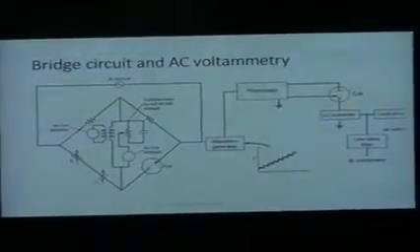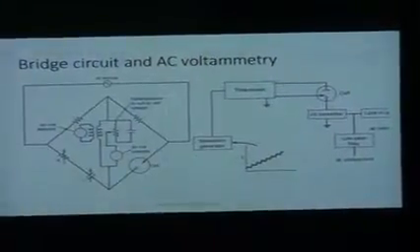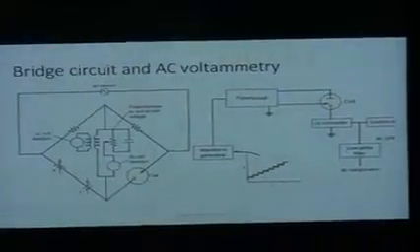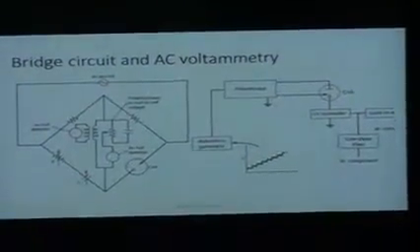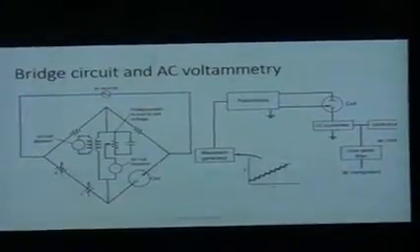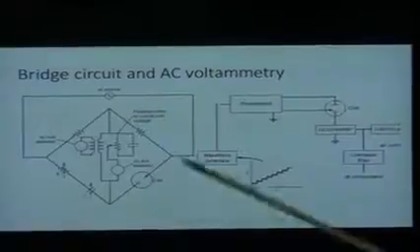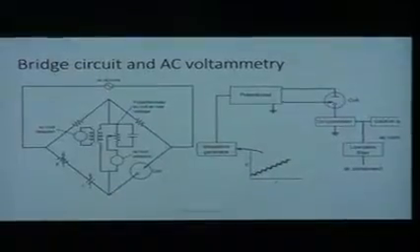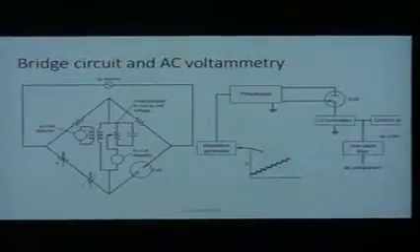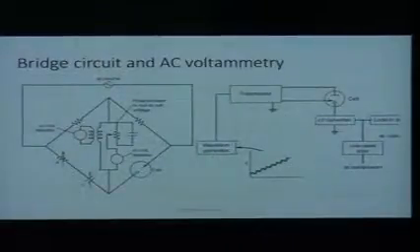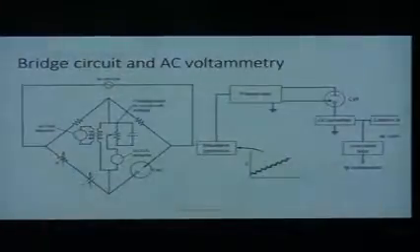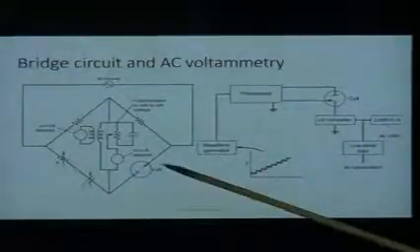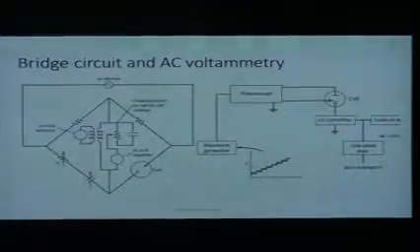So the way to measure this, there's a couple of different techniques or circuit forms that you can use. On the left, you have a bridge circuit. You might have seen that before. A bridge circuit uses variable components like a variable resistor and capacitor to balance out voltages within itself. And so it can send current from one side to the other, so that at the end, you can easily measure the voltages that are coming out of your cell, and you use an AC source to drive all of this, and you can look at the response of your device to different frequencies of an AC source.